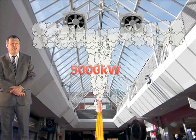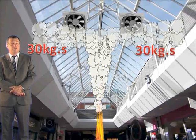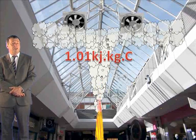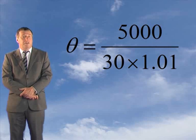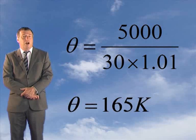Let's do an example calculating the average smoke temperature. If we have a convective heat release rate of 5,000 kilowatts and a mass flow rate of 30 kilograms per second, and the specific heat capacity of air is 1.01 kilojoules per kilogram per degree C, we have the equation as shown here. This predicts an average temperature increase of 5,000 divided by 30 times 1.01, which equals 165 Kelvin or 165 degrees C.